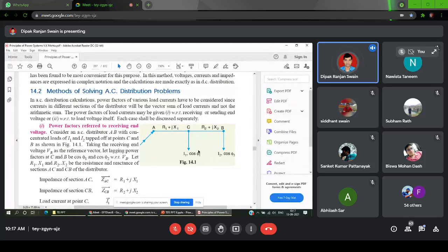Depending on this, power factor angle will change. So here in AC, you have to give the angle or power factor along with the current. In DC, we are only representing that at tapping A we have a current I1, at tapping B we have a current I2. But here, we need to take into account the angle also. So the calculation method is the same, only the calculations will be done in complex mode, using either rectangular or polar form depending on the use.